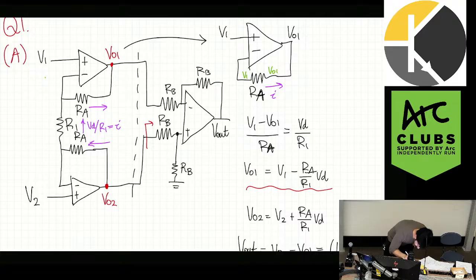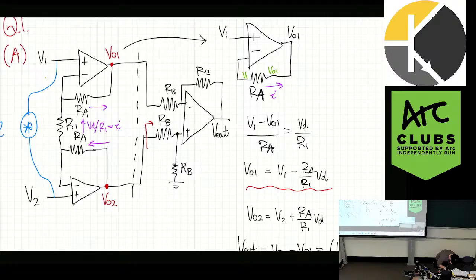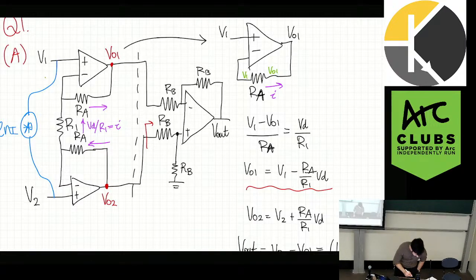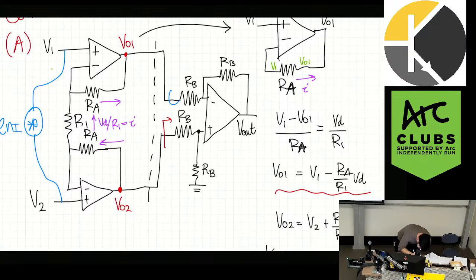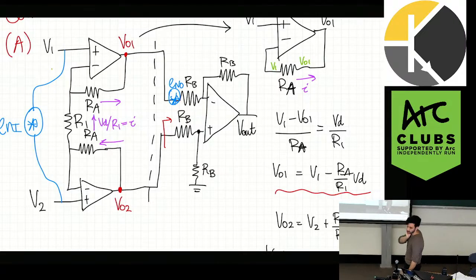What we have is noise sitting here. So ENI. This is the easy noise, right? Because it's already at the input. So there's nothing to worry about. It's cutting off a little, but anyway, it says ENI. The next noise is sitting at the second stage, so it sits here, somewhere there. I think they called it EN0, which is a bit of an unfortunate name, but EN0.